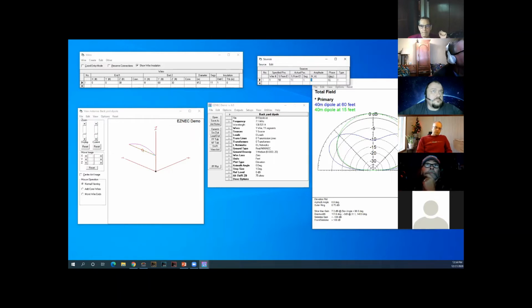And then you have 2 other parameters over here. One is called phase. When you have more than one source in an antenna, like a phased array, for example, you can specify the phase of each source, and then also the type of each source. For simple designs, we're going to use current, I, the letter I. There are voltage sources too. It doesn't really matter in simple models if you use a voltage or a current source. These are split sources, and if we have time, I'll get to that in a second.